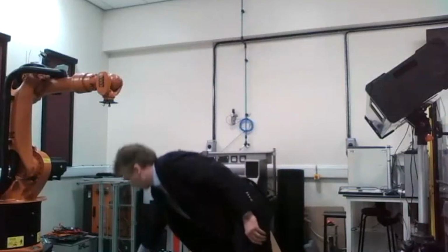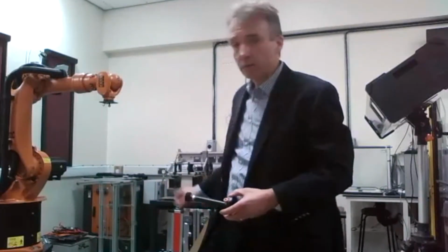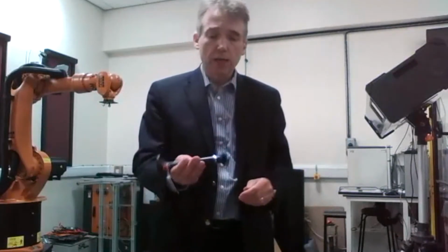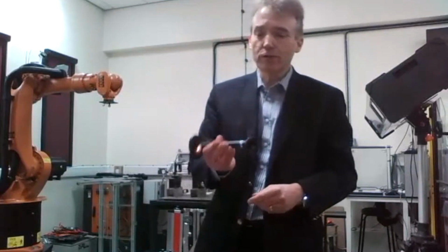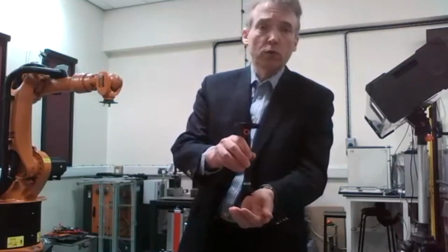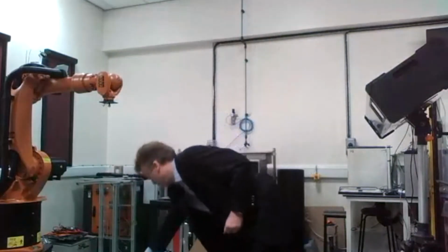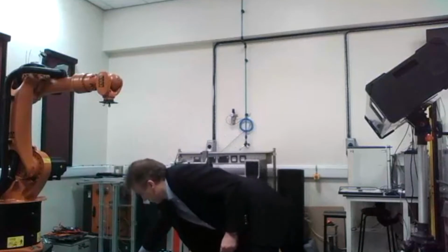And so the student had several tasks, several stages. One of them was mechanical design. How do you get the robot to actually pick up these wooden balls and then release them just above the cups that I've just shown you? So this is part of the solution. It's basically like a glorified drinking straw. There's a vacuum generator that was installed on the robot, which can be turned on and off under computer control. This is placed over the wooden ball. You turn the vacuum on, it grabs the ball, then it moves around. Turn off the vacuum, and the ball drops down onto the cup. So that's the theory.